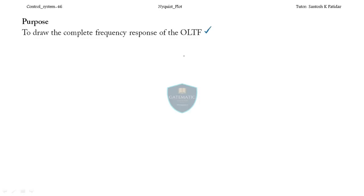What is the purpose? First, let me discuss this: to draw the complete frequency response of the open loop transfer function. So in the polar plot, we did not do the complete frequency response, only half of it. In this, we'll consider 0 plus and 0 minus also, both. Infinity also, plus infinity and minus infinity will be considered.